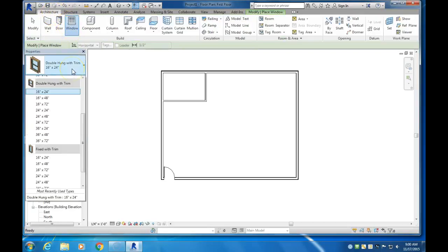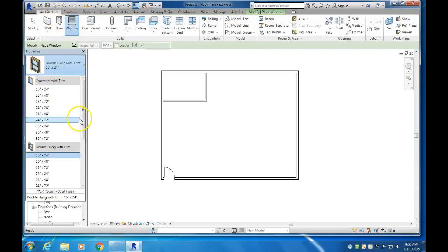For every bedroom, you need to have windows that can open, because there has to be a means of egress, a means of escape. One means of escape in a bedroom is a door. Another means is an openable window. So that's all part of your code, your building code documents. And egress just means escape. So make sure you have that in each of your bedrooms. And ventilation for bathroom, that would also account for that.